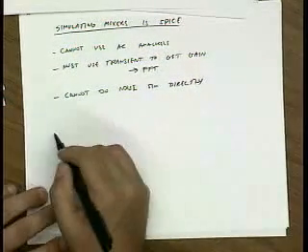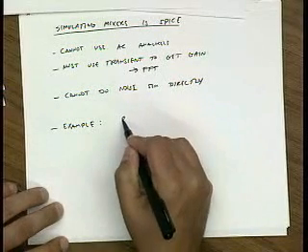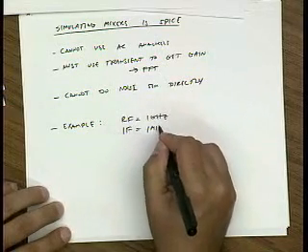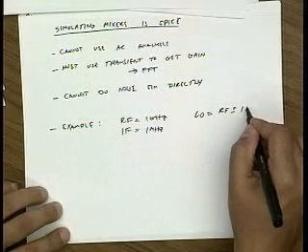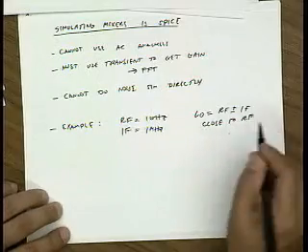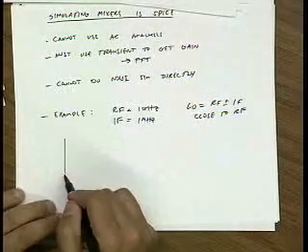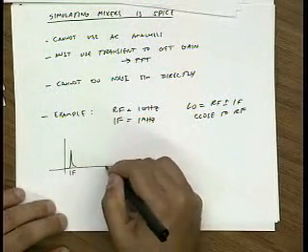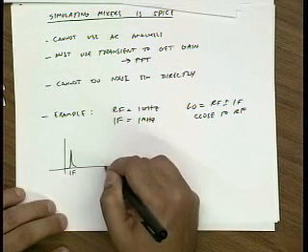Let's also look at the transient. Let's take an example. Let me assume that my RF is at 1 gigahertz. I'm doing a down conversion to an IF of 1 megahertz. And my LO, of course, is RF plus or minus IF. So it's very close to RF. So now what we need to do is we need to resolve several frequencies at the output. We need to resolve the IF frequency, and let's say we want to also find our RF leakage and our LO leakage at the output.